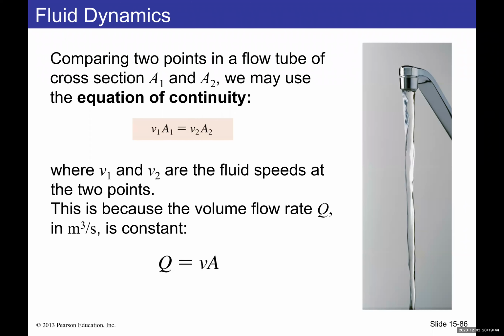All right. So taking all those three assumptions, when the liquid, most like a water-like liquid, is flowing at a constant rate, so the flow is steady, then I can assume that at any point that I look at, here's one point, another point, another point, I will find some quantity that is constant. And that constant is what we call a flow rate, Q. The flow rate Q for a laminar, steady-state flowing liquid will always be the same. And the flow rate is a product of the velocity of the liquid times the area.